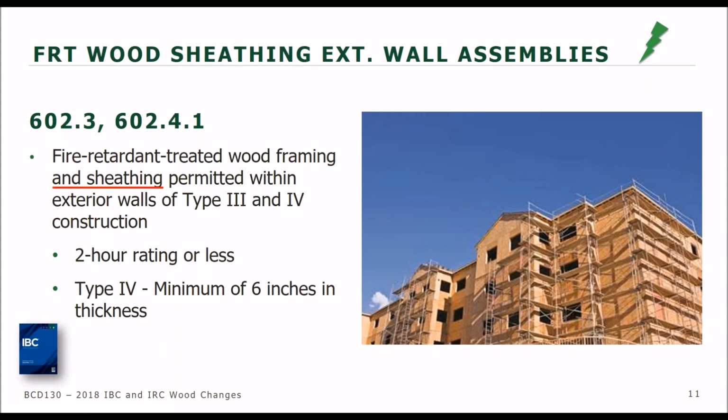We're going to be moving forward a proposal in this next cycle. So if you're in Columbus, you'll be watching for that to correct that correlation issue, to make sure that the 6-inch isn't a critical item. As you can imagine, when you're dealing with an exterior wall that has to have a fire resistance rating, it's the thickness that's required of the fire resistance assembly that's more important. Thanks. Great, good feedback.